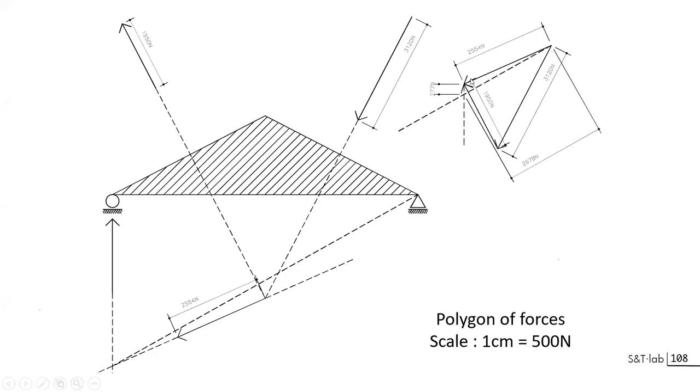And you know that this line has to be decomposed in a vertical force on the left and a horizontal force on the right. To position all these forces, that's very easy. You know that the resultant applied force is supposed to have an intersection point here. You know this direction, and so from this here you will know the intersection point with the vertical force. This intersection gives you the direction of the last support force.